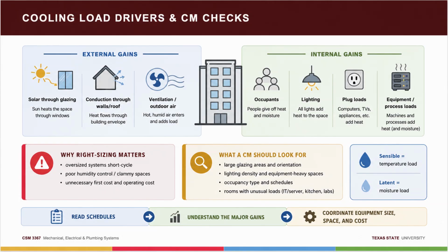Quiz alert. Sensible heat changes air temperature. Latent heat is the energy in moisture, humidity. Total cooling load equals sensible plus latent. If the quiz asks, which type of load do occupants add? The answer is both.